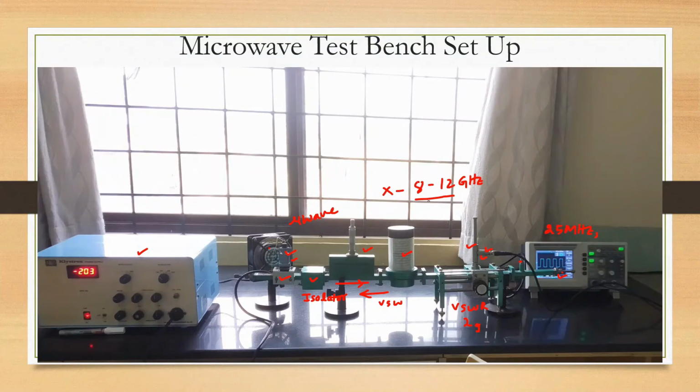Since we are not going to visualize this particular bandwidth of the signal, what we are doing is using this klystron power supply to generate an AM modulated, amplitude modulated signal. What it does is generate a square wave if the microwave signal is present, or else zero.